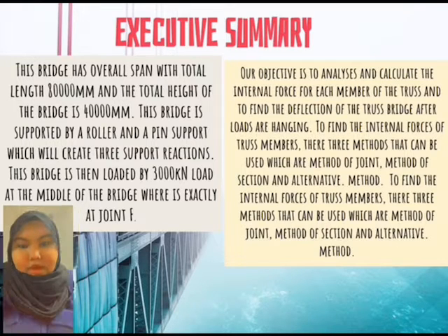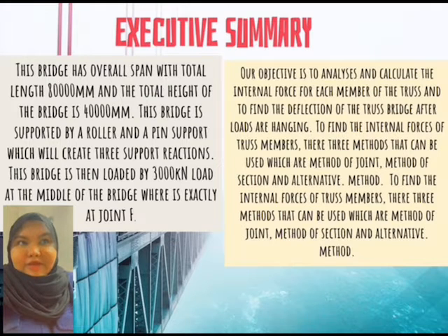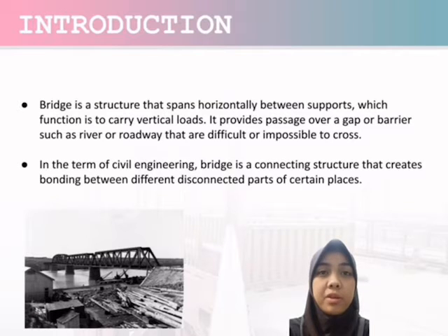The second point, our objective is to analyze and calculate the internal force for each member of the truss and to find the deflection of the truss bridge after loads are hanging. To find the internal force of truss members, 3 methods can be used, which are method of joint, method of section and alternative.